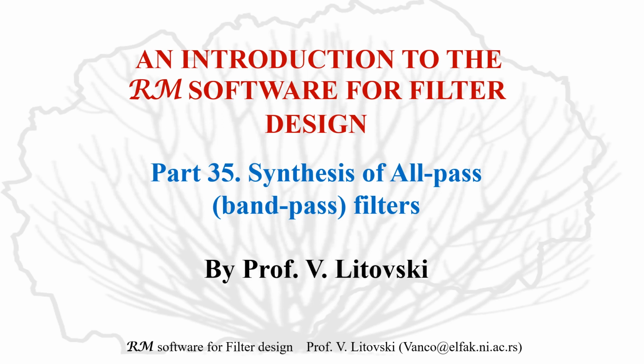The specific feature of this program is that the group delay is approximated in maximally flat sense, and that it allows for approximation of constant group delay and linearly rising and linearly falling group delay.